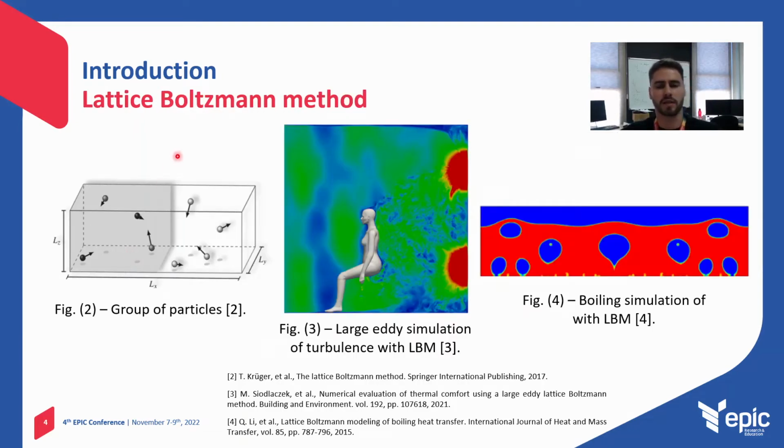So the numerical tool that we will use for this study is the Lattice-Boltzmann method. Different from standard numerical techniques that use the continuum hypothesis and solve the Navier-Stokes equations, the Lattice-Boltzmann method considers the fluid as a large group of particles, and it solves the Boltzmann equation, which describes the evolution of this system of particles.